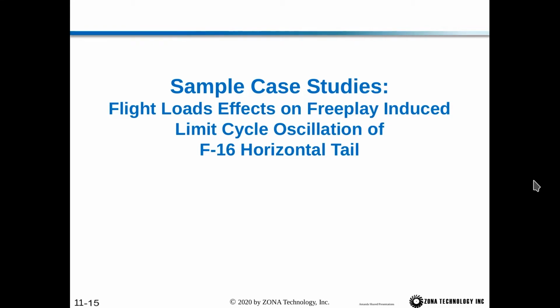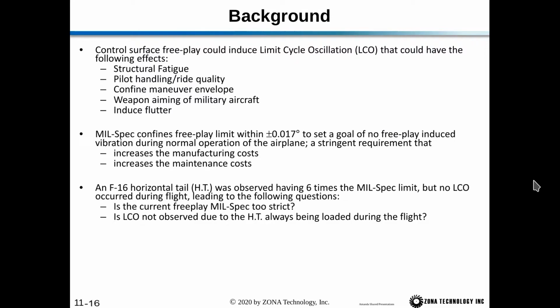So we'll continue looking at some more sample case studies. Next is the flight loads effects on Freeplay induced limit cycle oscillation of the F-16 horizontal tail. So our background here: control surface Freeplay could induce limit cycle oscillation, LCO, that could have the following effects: structural fatigue, pilot handling and ride quality, confining the maneuver envelope, the weapon aiming of military aircraft, and also inducing flutter.